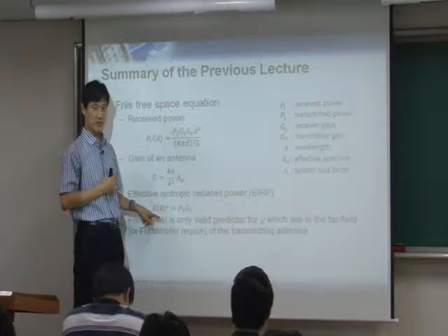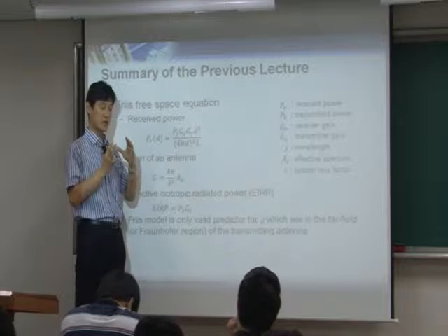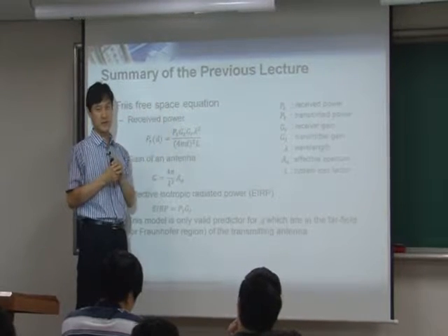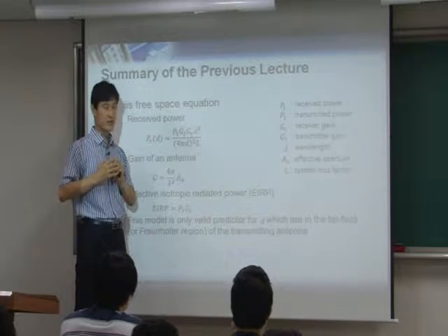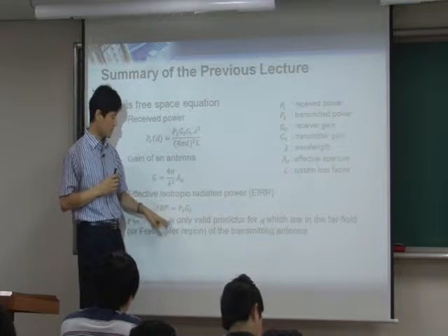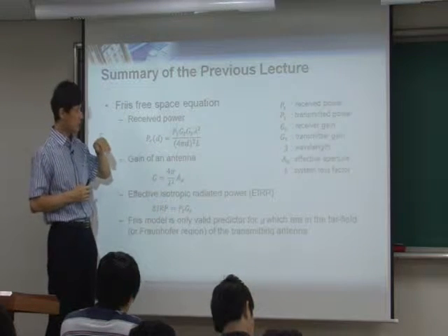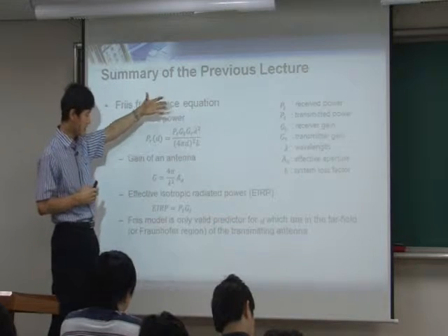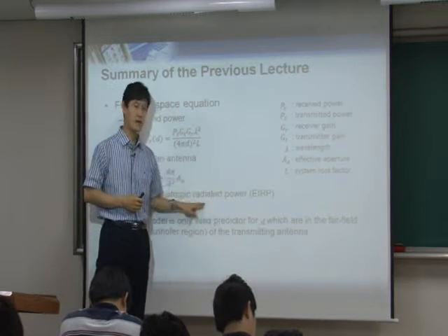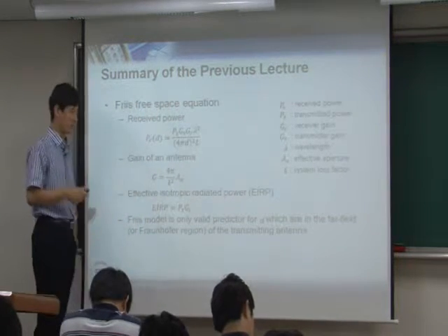That's EIRP. So EIRP is the actual transmit power in the air, not the power that you wanted in the system. That's PT, right? But EIRP is the actual radiated power, okay? That's EIRP. That's a little bit different sometimes.